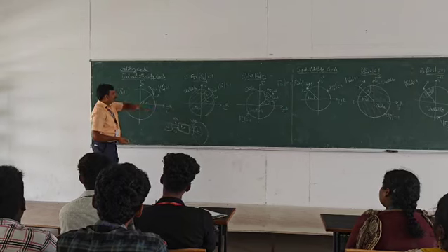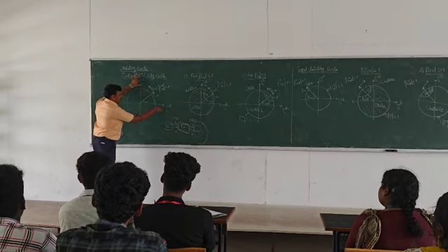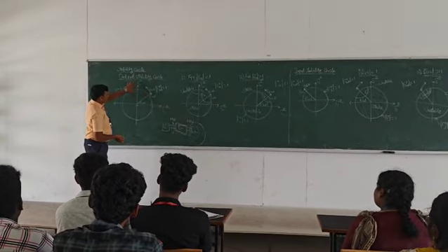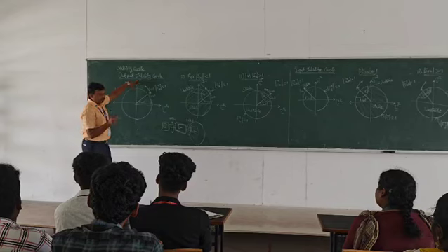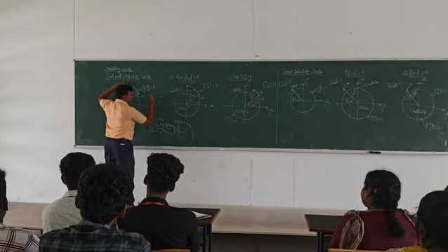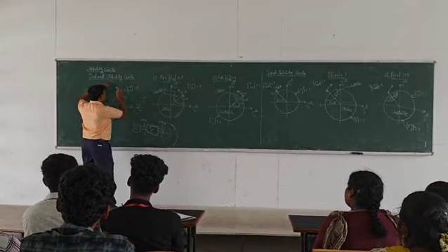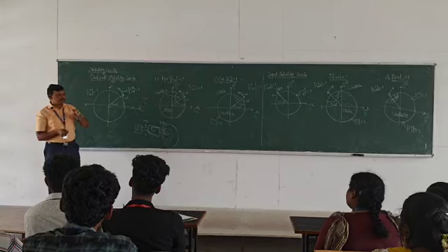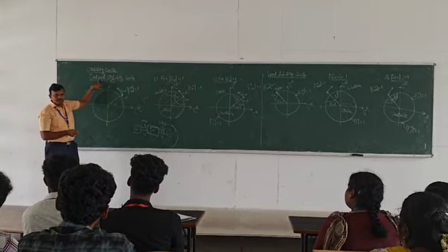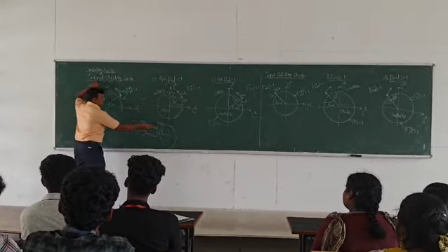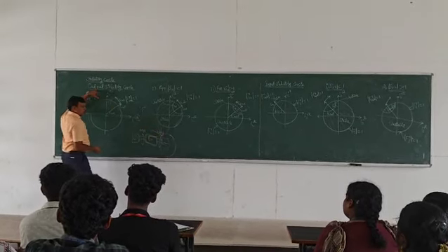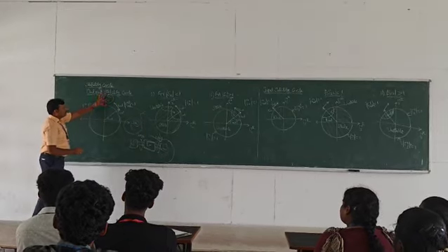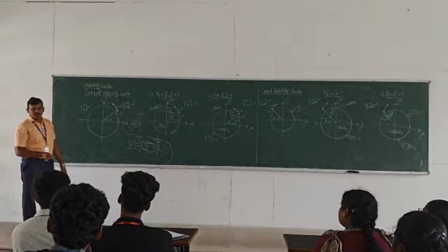For the load, the x-axis is the reflection coefficient at the load, and similarly the y-axis is the reflection coefficient at the load. Gamma is nothing but the reflection coefficient. This is the resistance and this is the reactance. Both are maintained at the load only, because we are looking at output stability, so we focus only on the load side.